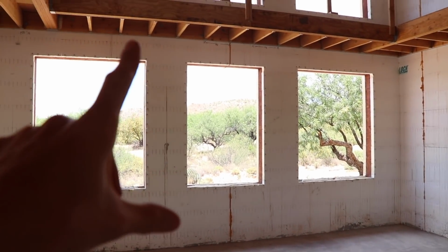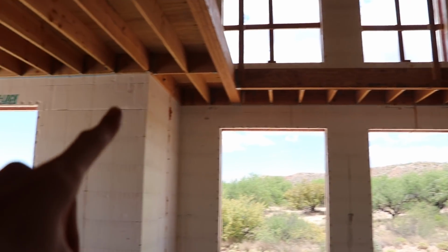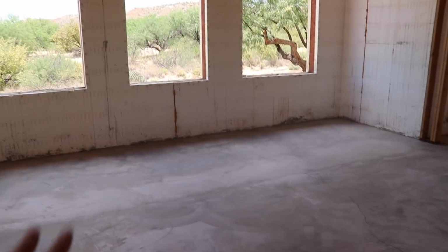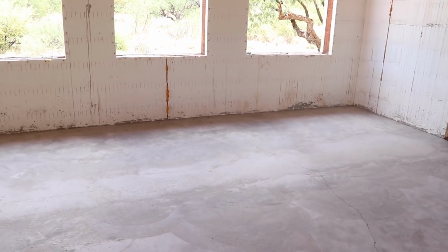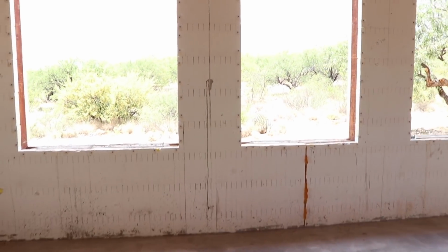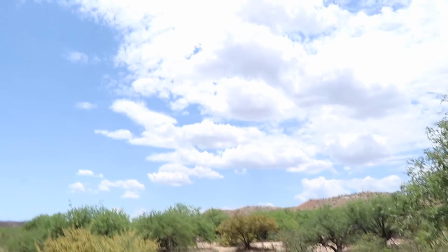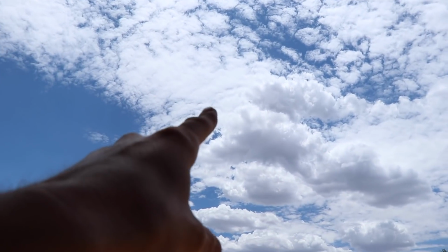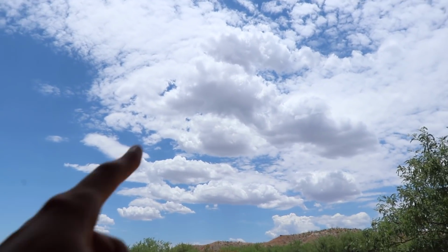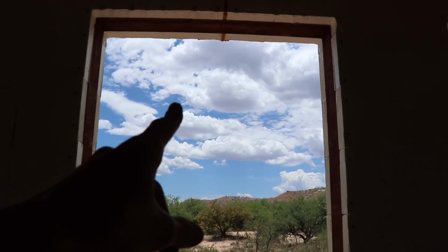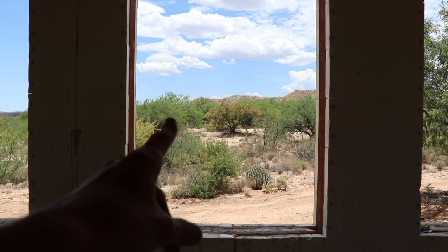Since we're not going to be getting any direct sunlight through any of these south-facing windows here, it's going to keep the space inside much more cool and comfortable, especially during the summertime. Now, when it's more wintertime, that sun is going to be much lower in the sky. So as the sun is lower in the sky, we're going to actually get quite a bit of thermal gain through those windows, and the concrete slab here is going to act as a heat sink, and that'll help keep the house much warmer during the winter time.